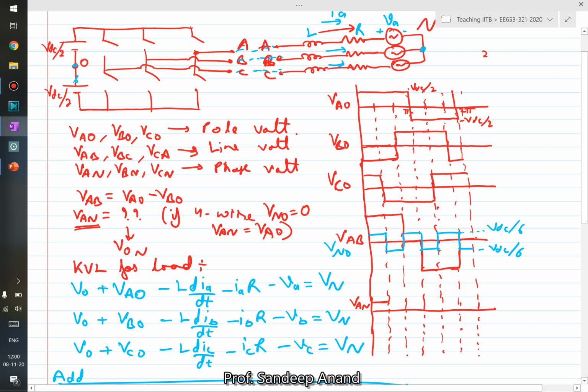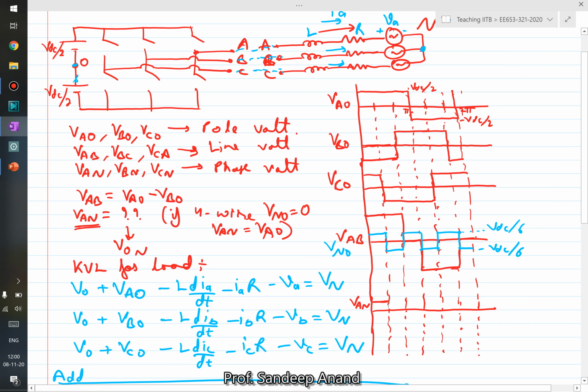In the second period, VAO is the same. VBO is minus VDC by 2, and VCO is also minus VDC by 2, whole divided by 3. So this is approximately 2 VDC by 3. So the first one was VDC by 3, and this one, let's say, is 2 VDC by 3.